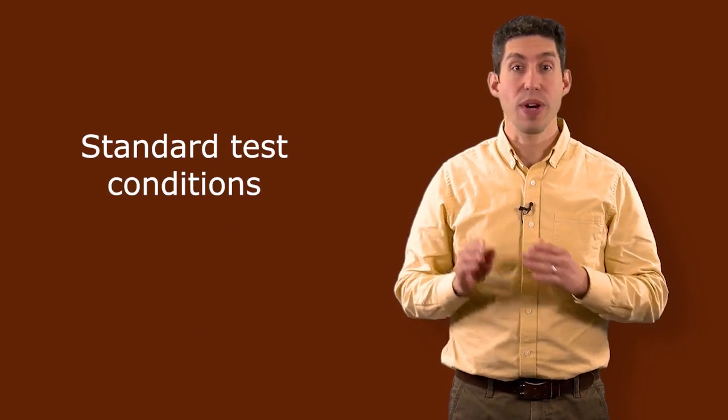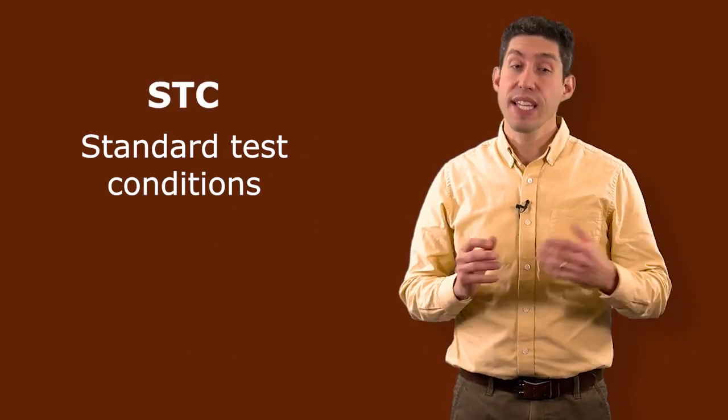We'll review those now. One of the test conditions that we've discussed before is known as Standard Test Conditions, or STC. Standard test conditions are defined as an irradiance of 1,000 watts per square meter and an air mass of 1.5 with a module cell temperature of 25 degrees Celsius.